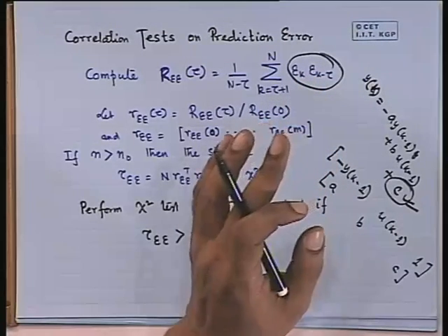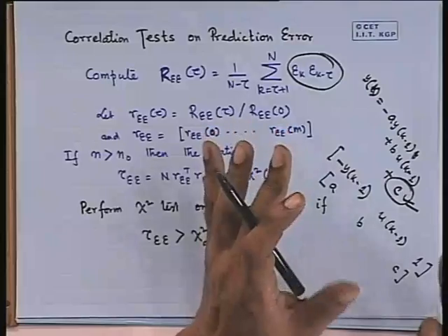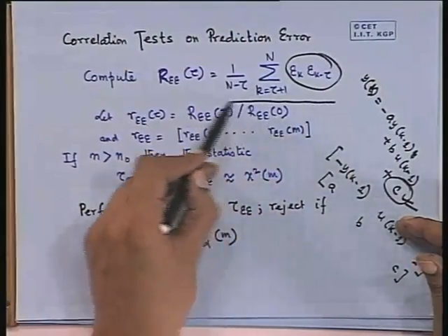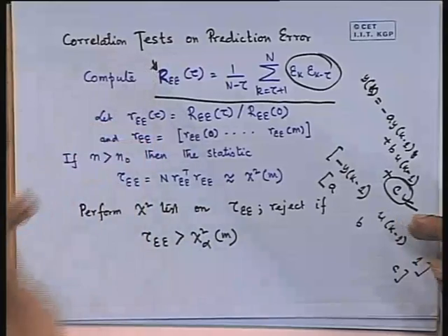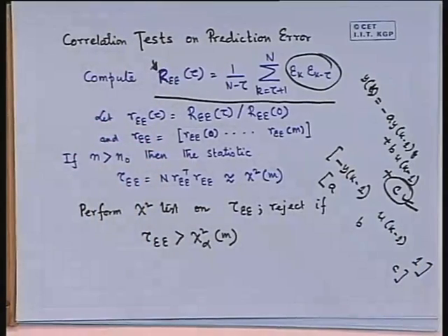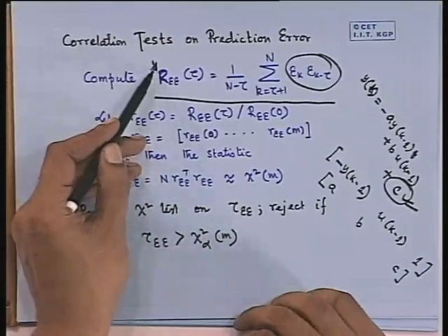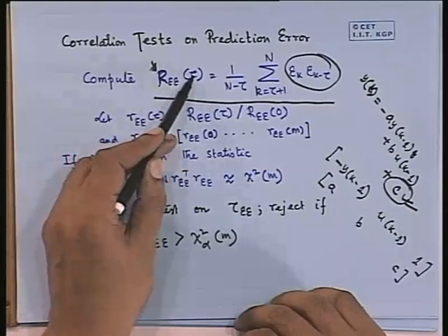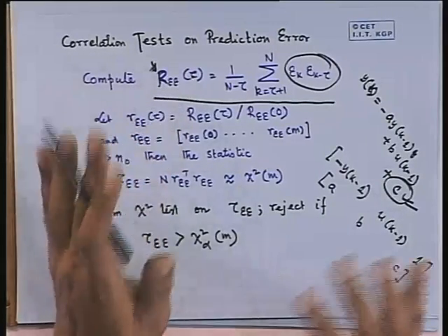Okay. So it is expected that you have modeled the regular properties, then whatever remains should be uncorrelated. That is the expectation. Again, remember that if you compute this from your data, you will get a sample. The basic principle is the same. You want to test for whiteness: only for r epsilon tau equal to 0 you will get some correlation.